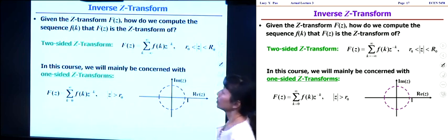Okay, now, so we've talked about the definition of the z-transform, a number of its properties, and ultimately, when you're solving a difference equation, you take a z-transform of the difference equation and do algebraic manipulations, which you'll do by using a lot of the properties of the z-transform. You'll get at your u of z, the z-transform of the desired time domain function.